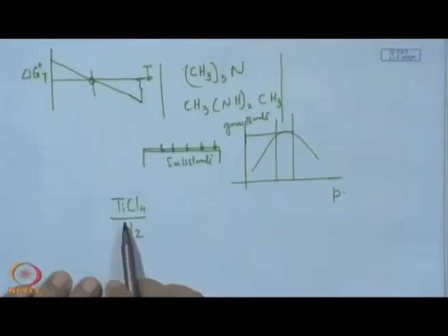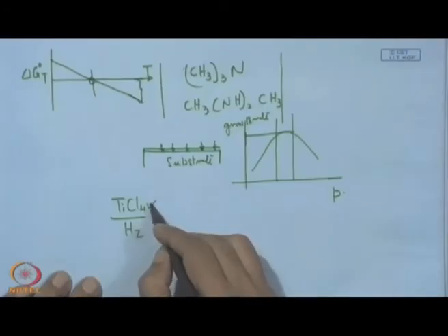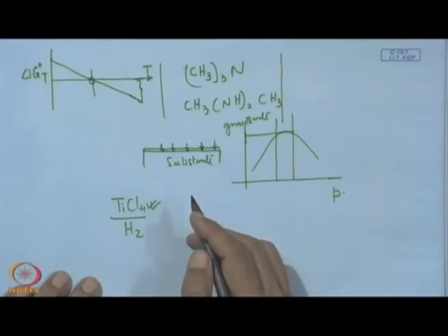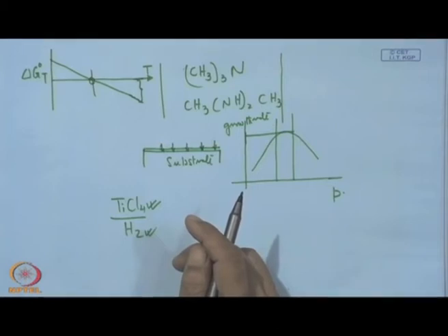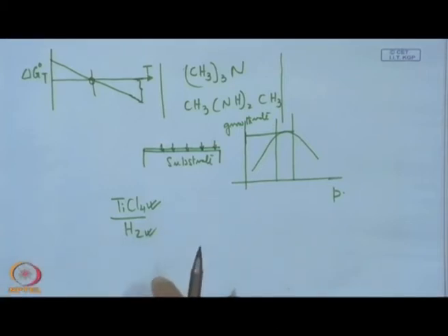If it is not done, then we may have excess of HCl, and this HCl may revert the reaction, and then the reaction, instead of being product favored, becomes reactant favored. So, there also we have to pay attention to how to increase that TiCl4 with the increase of H2 if we like to have enhancement of the growth rate of this coating.